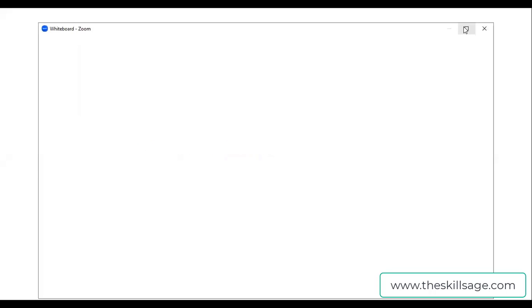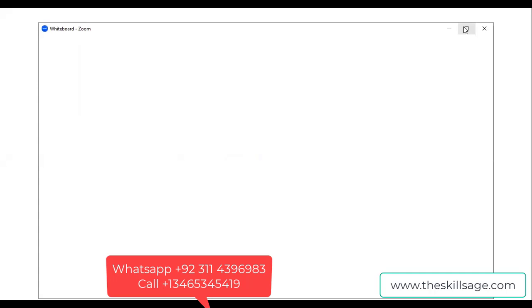I'll share the whiteboard with you. Don't worry, I will share what I need to do. There is one activity this way: HVAC system design, then there is procurement, then there is installation for a single item. So dependency means that if design is done, then procurement can be done. If procurement is not done, then installation can't be done. If my procurement is not done, I cannot proceed to start the installation activity. So dependency is very, very important to show in my Primavera P6.